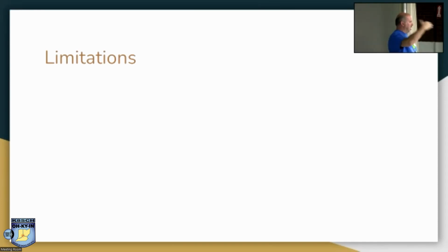So if you put an inductor on there, you will just see inductance. You put the capacitor on there, you'll just see capacitance. Resistance, you'll see resistance. If you start combining them together in all these cool patterns, tank circuits, yes, you will begin to see those characteristics. So the idea behind this piece of test equipment is that when you design something, you can verify that what you built matches your design, that you're seeing the performance as expected. You're seeing the return values coming back. You're seeing the phase angles coming back.